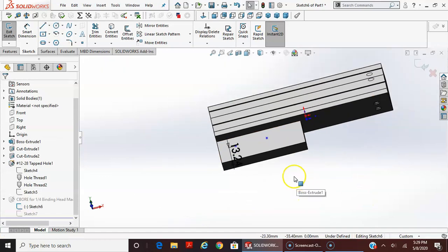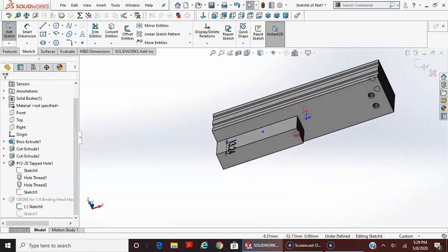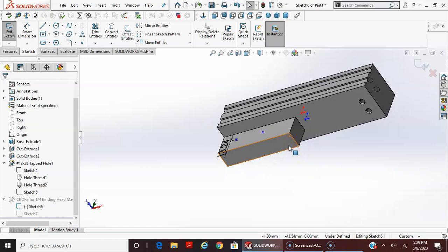It might be hard to tell on the drawing, but on that particular drawing, on the counterbore holes, the counterbore actually violates the radius of the edge. It's kind of got a large radius there. But that is correct. And if you look real close on the drawing, I think you'll see that. So don't be surprised if part of your counterbore feature is cut away based on the radius edge of the part. So I think that's it for now.